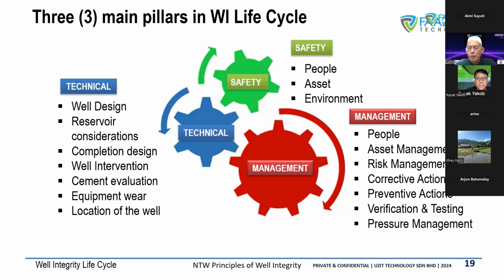For P&A, the well, we have to restore the well for 100 years, for example. So you have to put in something that is permanent. The industry accepts that cement is considered a valid barrier because it can last for 100 years. But if you put in a bridge plug, it's not considered a barrier because it can deteriorate and has a field life. So during P&A, it's a totally different ball game, a different definition of well barrier. Interesting, eh? Many variables, many conditions.